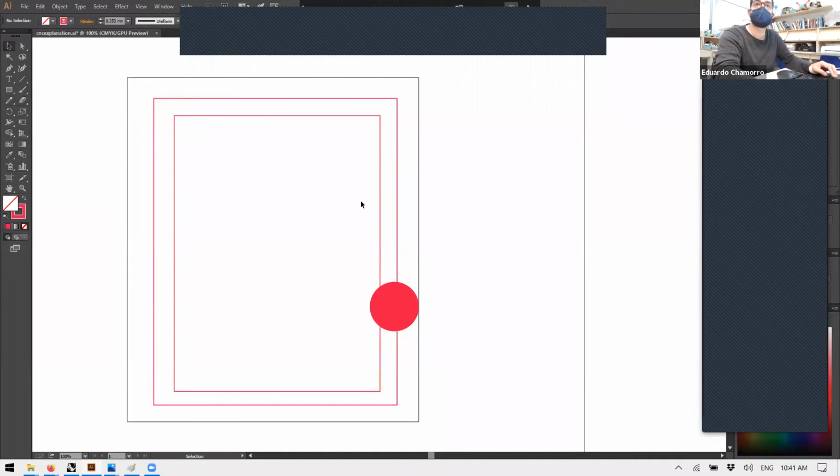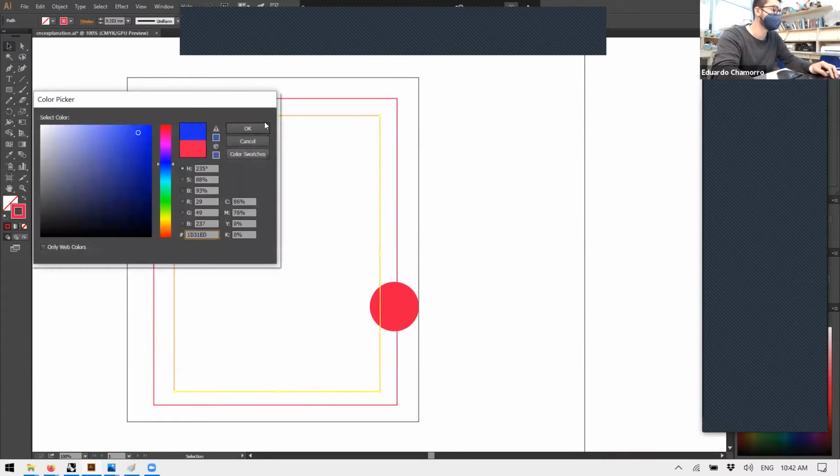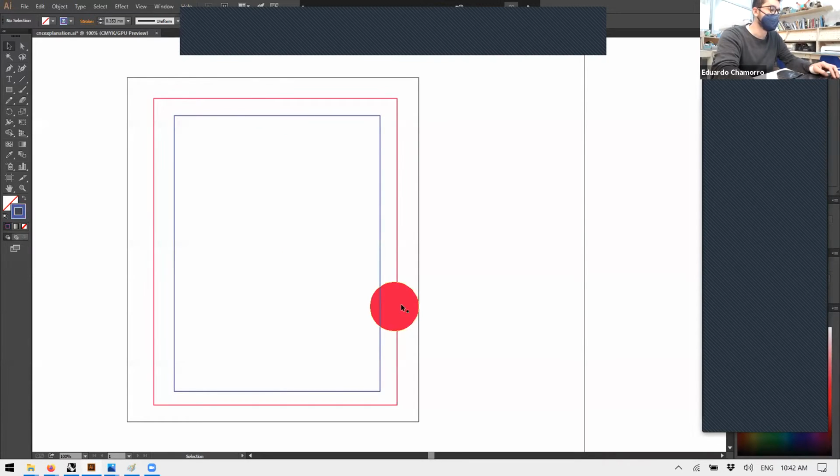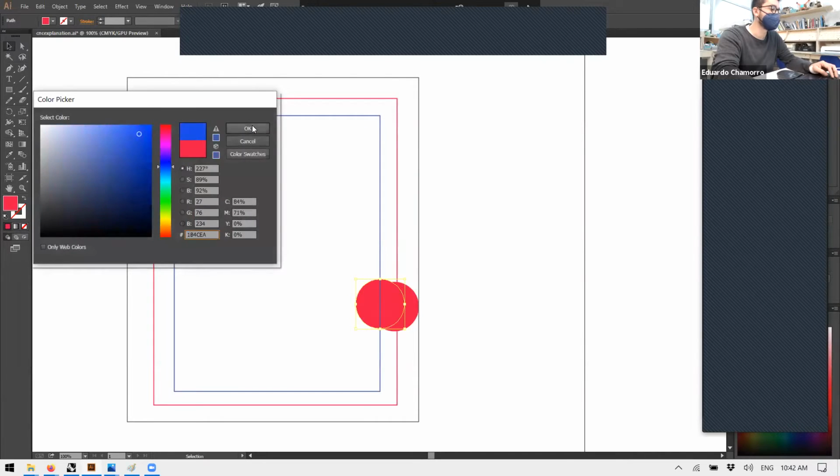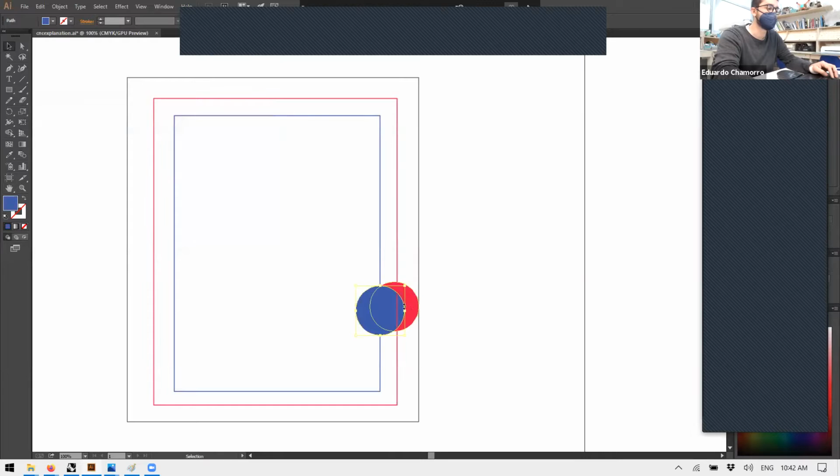These are automatically generated. This is what is called the toolpath. And it's going to make the next offset. The amount of offset, or the total amount of movement that we do on the side, is called a step over. How much you move on the side.